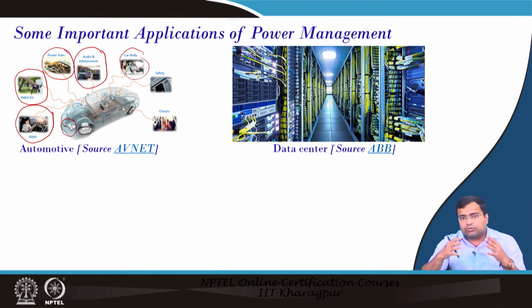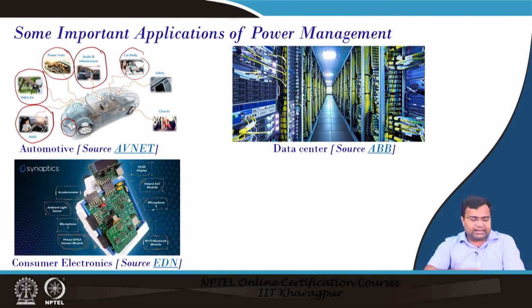If we are talking about low voltage high current applications, the voltage level can be 1.8 volt or below, and the current can be several hundreds of amperes, or even more than 1000 amperes when you are talking about the cloud server. So, for such applications, there is increasing use of digital control for power management control ICs, and we will take some example case studies.